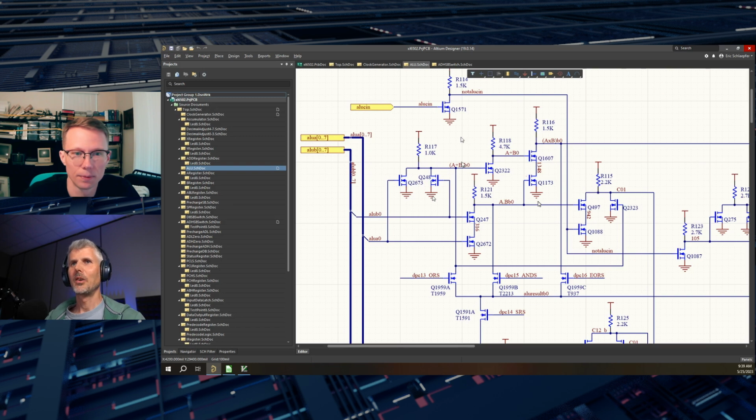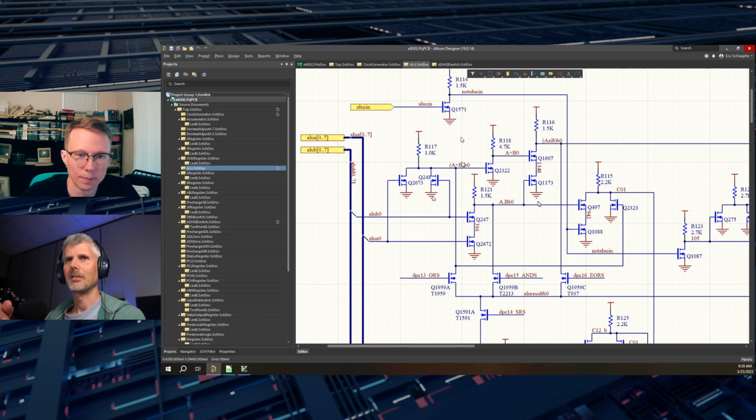Yeah. Okay. So you mentioned something interesting there about fan-out. With the ASIC tools that I'm used to using, that's all taken care of automatically for me. So you get like a resizer that will go through and change a 1 drive strength inverter to a 4 drive strength inverter or whatever. Or for clock trees, you have special buffers that can drive things extra hard. So how did you work out where you needed to add more transistors to gang up the extra drive strength?